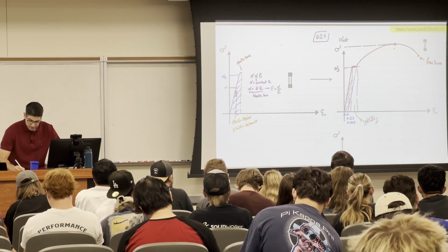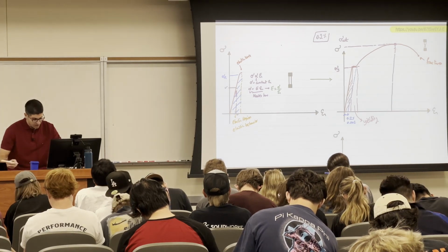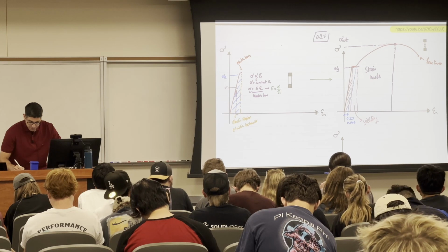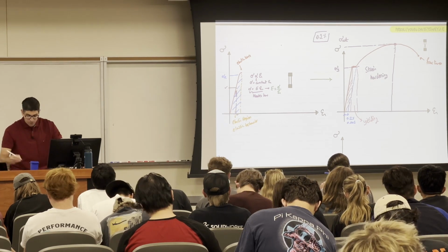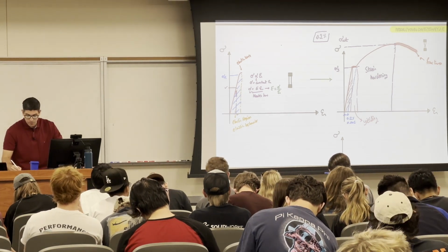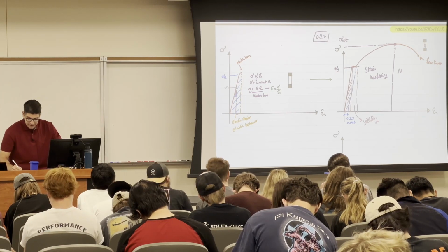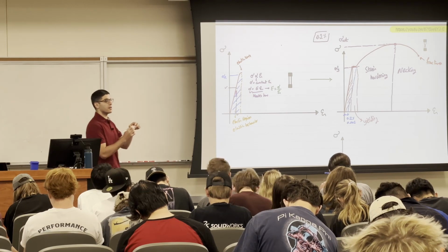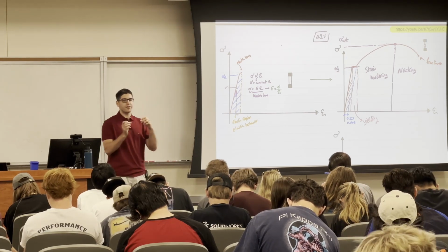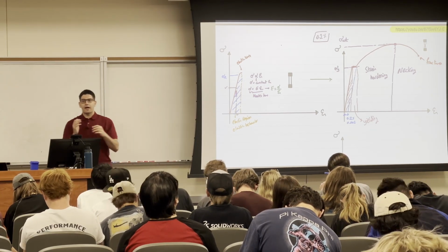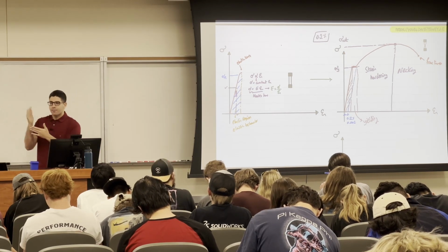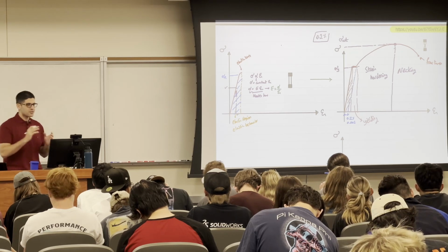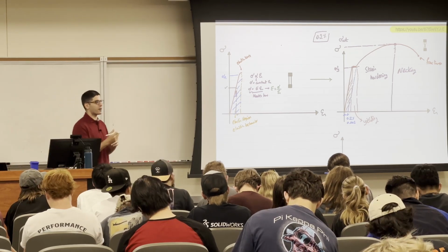And we can divide it from here into two regions. This is something we call strain hardening. And after that, when the material starts to fail, that's what we call necking. You can see an obvious necking in metals, from what you saw in the video. That's when you know, as if it's a warning that, hey, I'm going to break, so you need to leave the building. So we love this kind of material that gives us an indication that it's going to break.